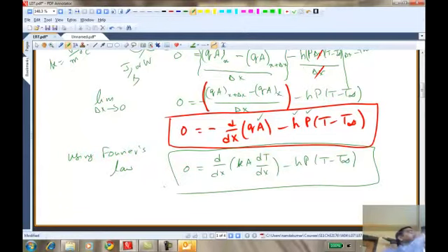Yeah. Do you know T initial? A good question. What is T initial? T infinity is the room temperature, which we know. So would it be that? Or is that the right question to ask? Initial temperature, it would be if I'm dealing with a transient problem where the fin is initially at room temperature and I bring the base to 200 degrees at time t equal to 0, and the temperature keeps on changing over a period of time.